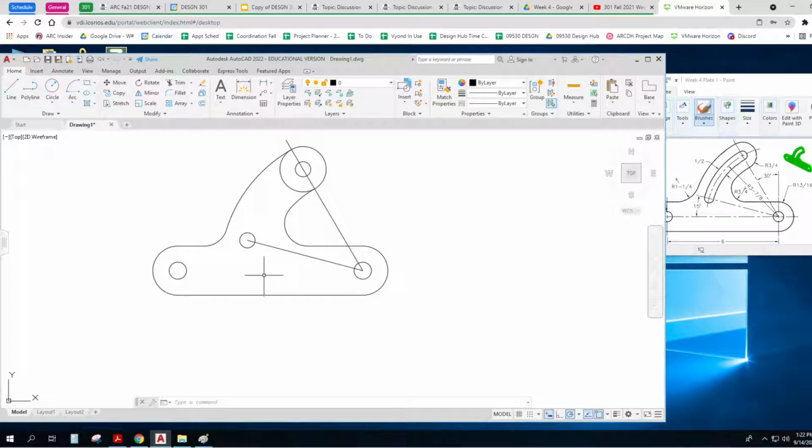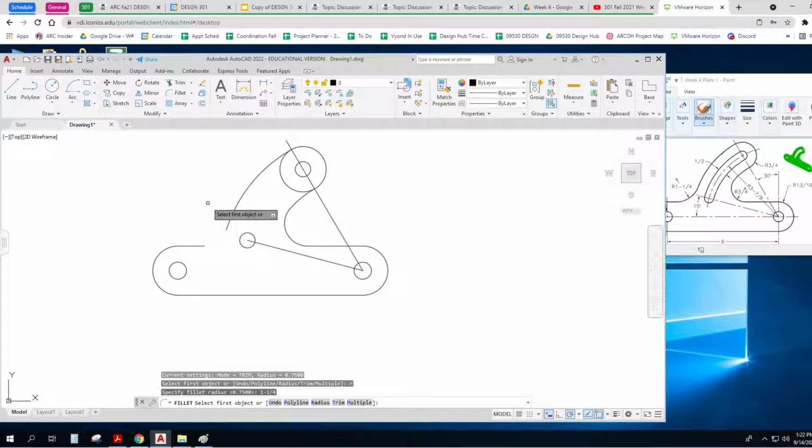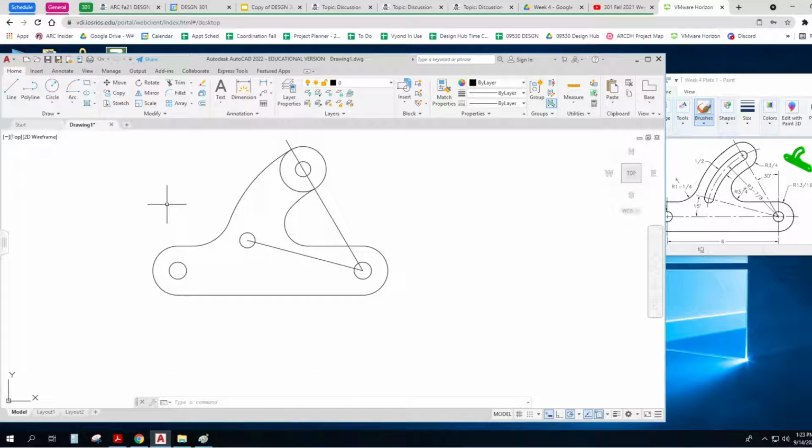So here's how you fix it. That's a great point. Watch this. Click, get rid of it, and just put a new one in. Fillet, R, 1-1/4. That's what I love about AutoCAD. If I had done that in the working world before I had AutoCAD, I would have had my eraser out, and they had those spinny ones, and I had to erase it. And then, if my boss came over and could see the eraser marks, then they were mad. There we go. That one's better. Thank you very much, Richard, for catching that for me.